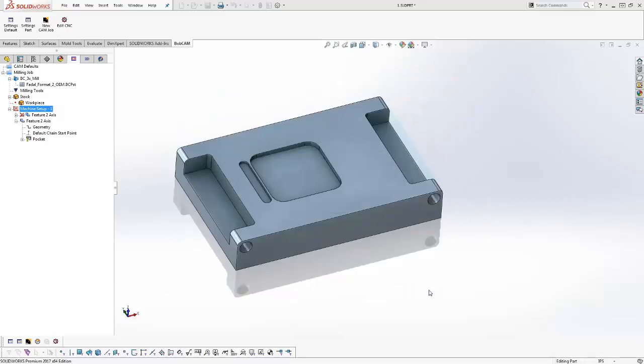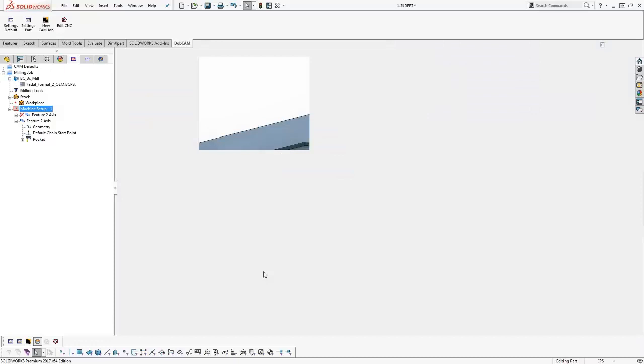And then compute. And the cool thing with BobCAM is it's going to know that that boundary intersects with the stock geometry. So that tells it that it's open, and it will just machine from the outside, okay? So I haven't launched simulation. Let me go ahead and open simulation up.